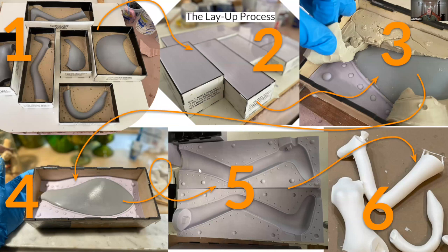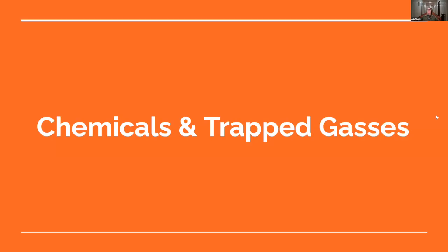These are flexible, and these were 3D printed parts that were the prototypes. And it lets you control how they come apart. However, this is a very time-intensive way to do this. A lot of times you'll just do a solid block of rubber and cut it open to get the part out. Okay. But it's great for production molds because they last a really long time and they give you a super precise parting line.